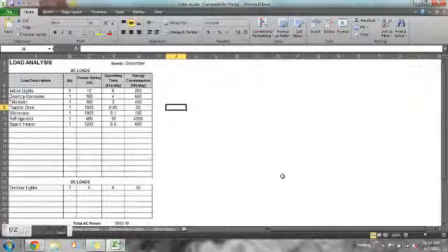There are four critical processes necessary to design a standalone PV system. The first step is the load analysis. In the load analysis, you determine the magnitude and duration of all your AC and DC electrical loads on an average daily basis. The second step is to do a critical design analysis, in which you will find the critical design month. This month is the month with the highest load demand and the lowest insolation.